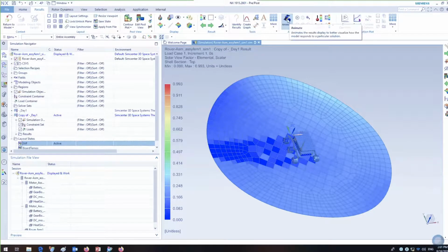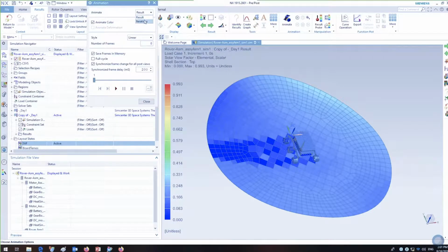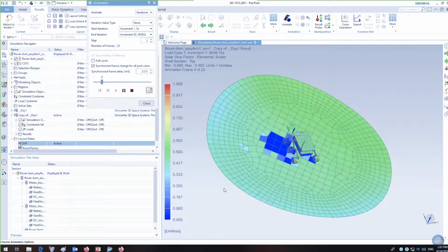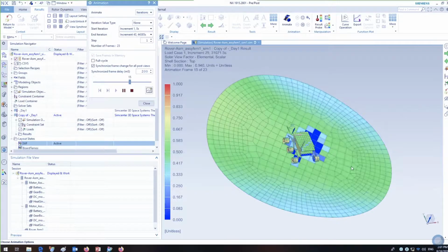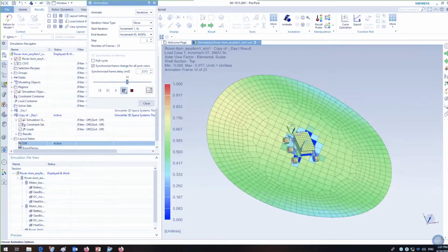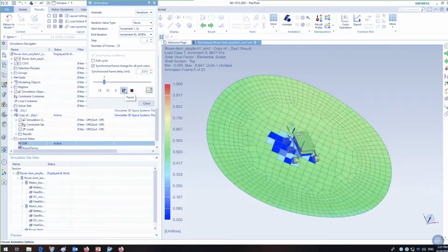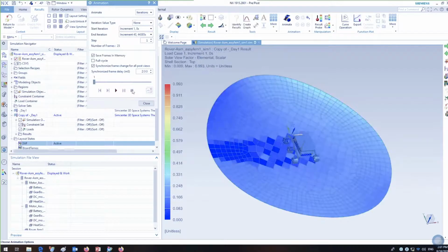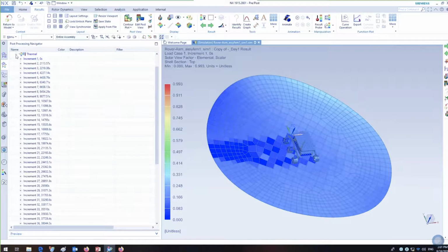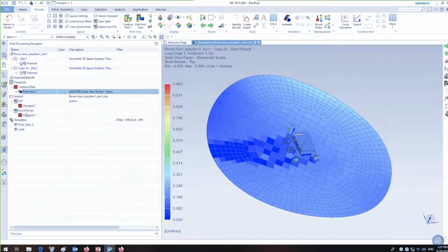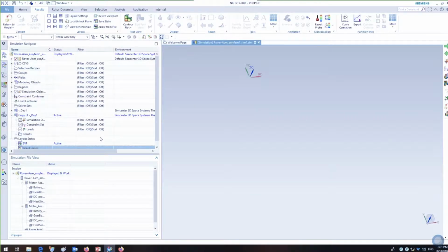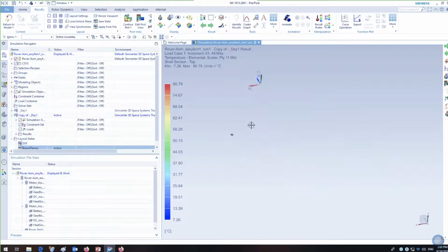And so we're going to get the board temperatures in the context of the rover, taking into account the solar heating. So this is the model. We're looking at the solar view factors on the rover. As the Martian day goes by, we can see the shadow moving across the Martian surface here. And that's all calculated by the SimCenter 3D Space Thermal solver.